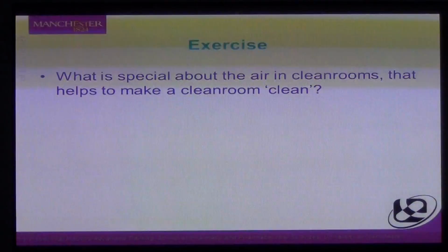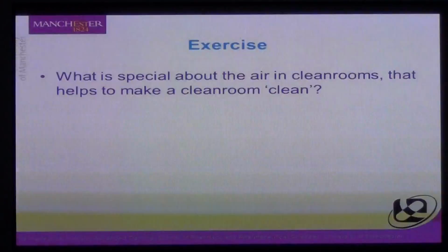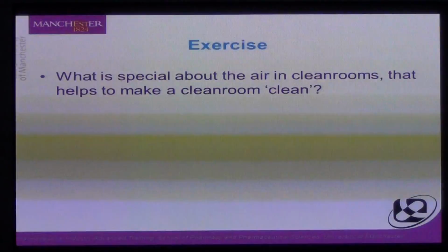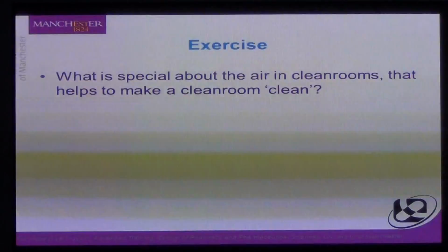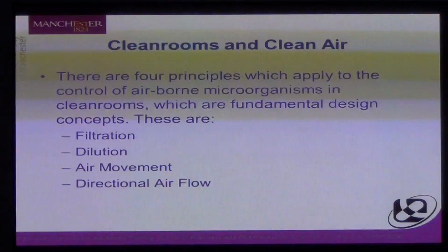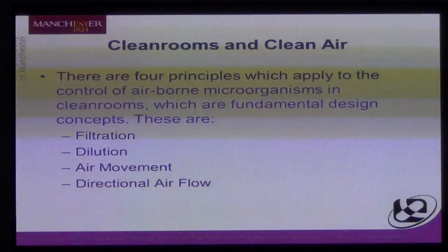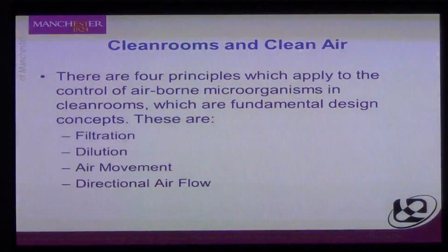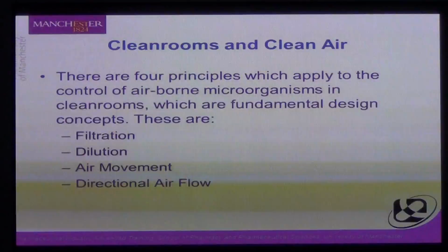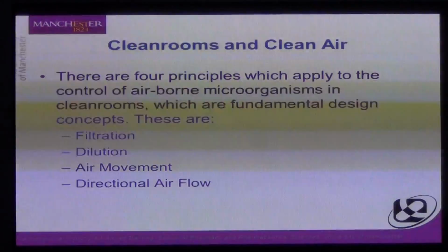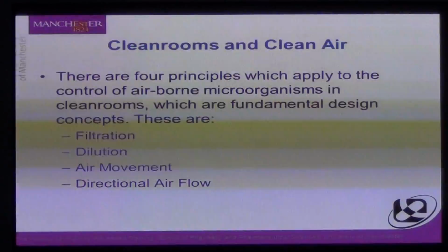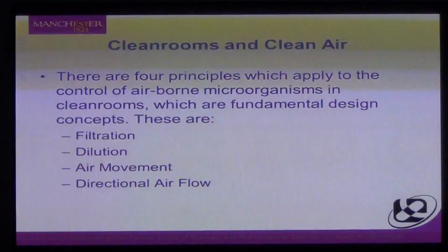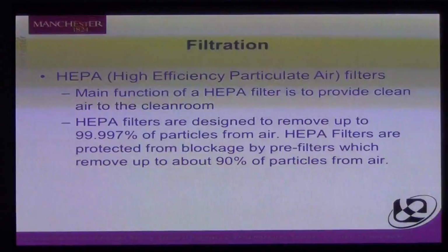Welcome back. So that was your question. What's special about the air in clean rooms? Hope you had some reasonable answers. Here are a few of my thoughts. To me there are 4 principles which apply to the control of airborne microorganisms in clean rooms. Essentially, these are fundamental design concepts, and these concepts are filtration, dilution, air movement, and directional air flow.